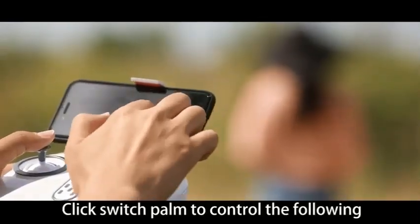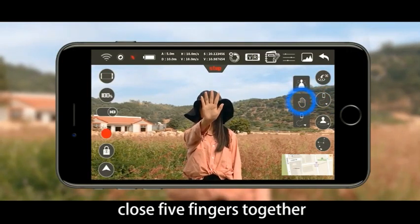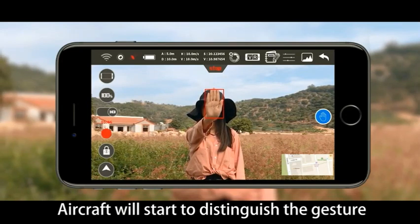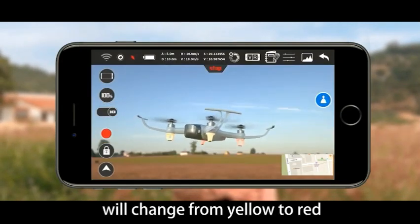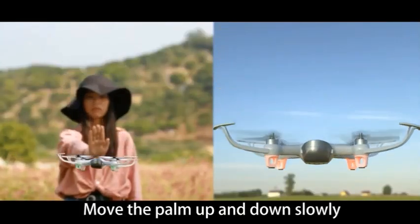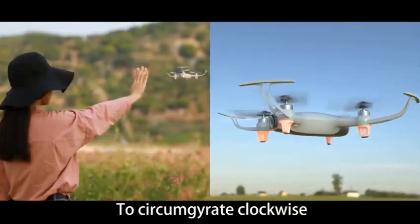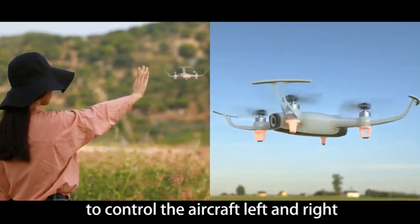Click Switch Palm to control the following. Fly single hand, close 5 fingers together, point to the head of the aircraft. Aircraft will start to distinguish the gesture. The rear indicator will change from yellow to red, which means following successfully. Move the palm up and down slowly to control the aircraft up and down. Circumgyrate clockwise or anti-clockwise to control the aircraft left and right.